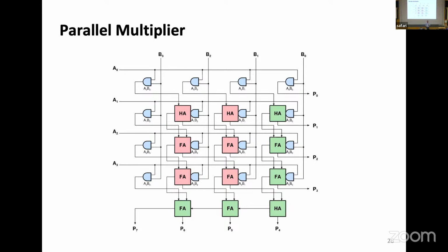There are also processors where they say, I don't want a multiplier, and I'll do the multiplication in software. Because it's the same operation, you can also do it: I AND things, I shift them, I add them, and if you take 30 steps, you can do that. But 30 steps takes time. So that's also a trade-off you can make.